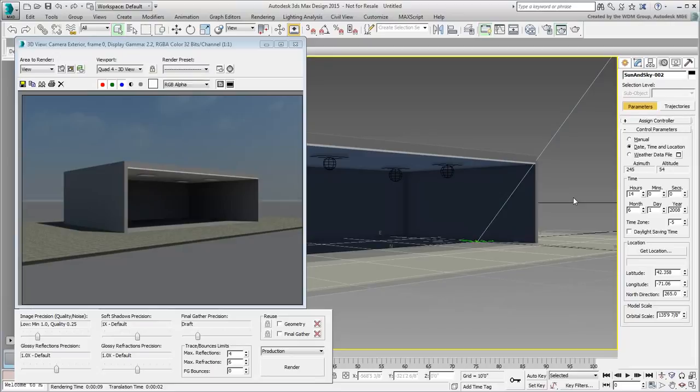You can see the effect of direct sunlight and shadows. You can also see the effect of global lighting as it illuminates the surroundings and the inside of the room. This requires tweaking as well. Notice also the background, as it shows a sky with few clouds, as specified in Revit. Let's see how we can make things better.